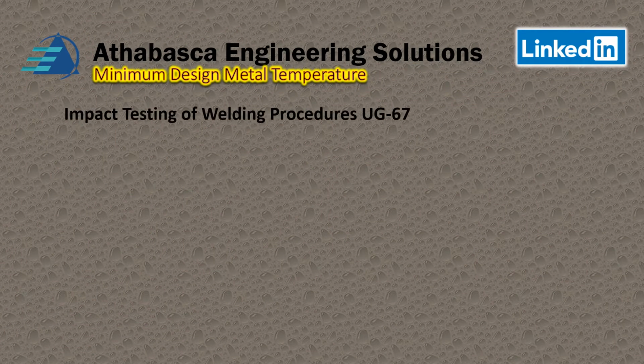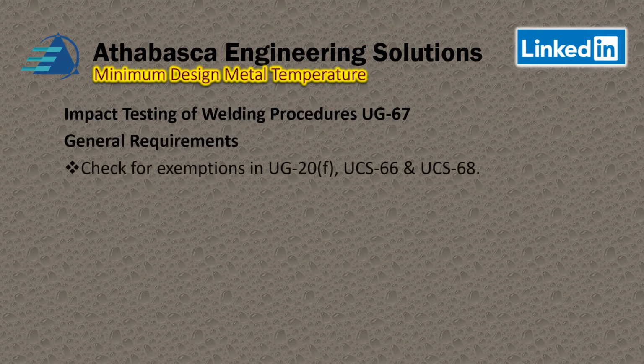We're going to begin with impact testing of welding procedures as described in UG 67. So general requirements. Check for exemptions, first of all, in UG 20F, UCS 66 and 68. These were described in the part 1 and 2 videos.